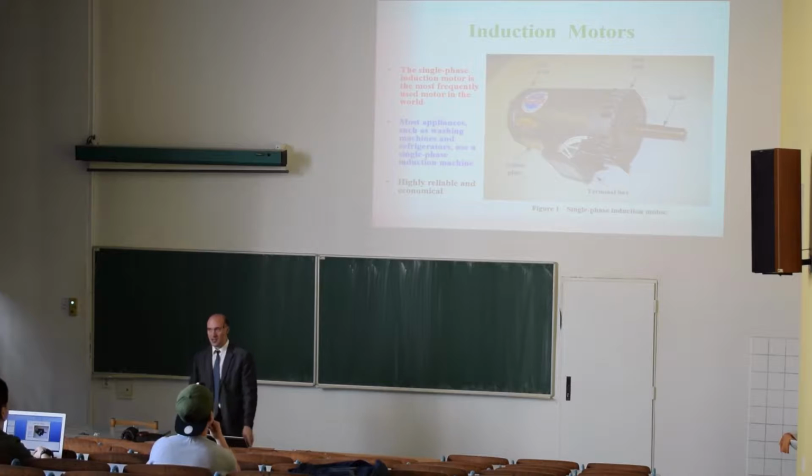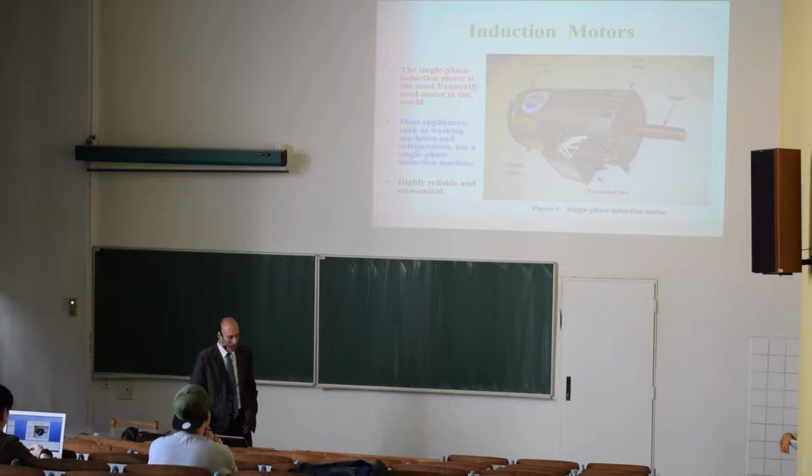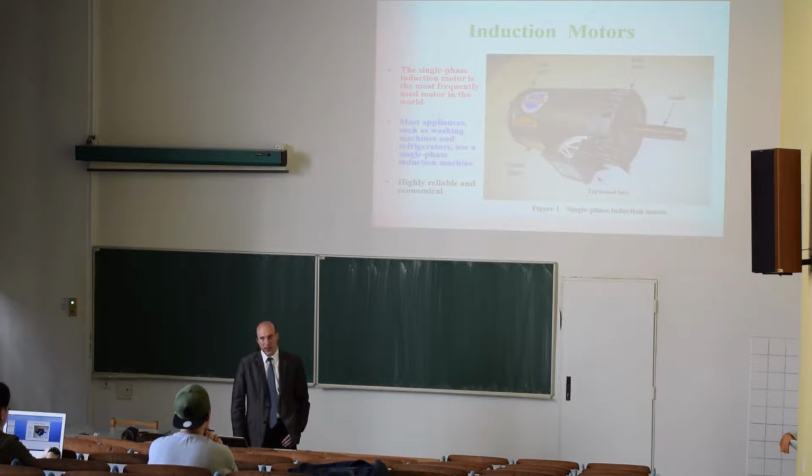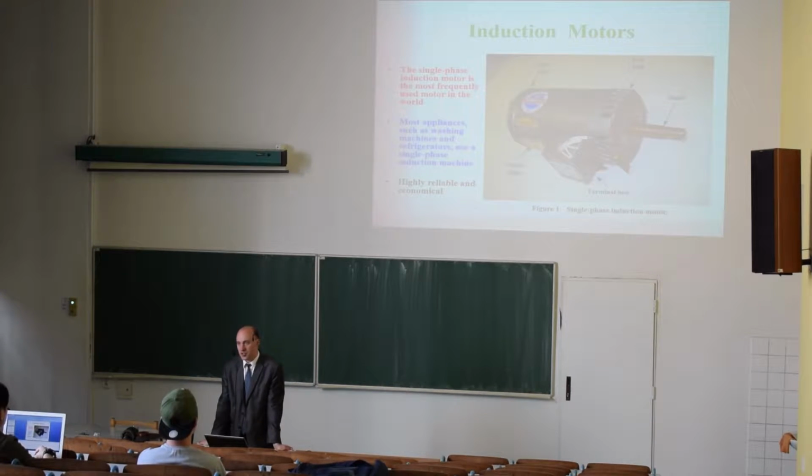As we have seen, for the last 2 lectures, we have discussed DC motors. DC motors have a commutator. They need mechanical contact between the rotor and stator. But induction motors have a very simple construction, which means that they can be manufactured very easily. They are less prone to mechanical damage, mechanical wear, and they also have typically higher efficiencies.